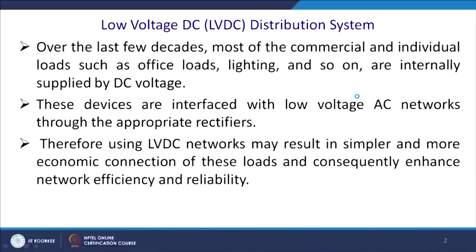So, the issue is that over the last few decades, most of the commercial loads, such as office loads, that means desktops, laptops, lighting, these are LEDs and so on, are internally supplied by DC voltages. You may have a big LED TV that is internally supplied by a DC supply, and thus these devices are interfaced with the low voltage AC networks through appropriate rectifiers.